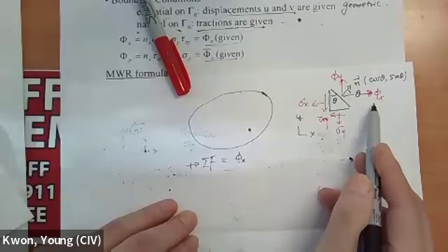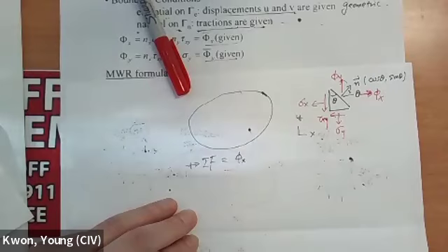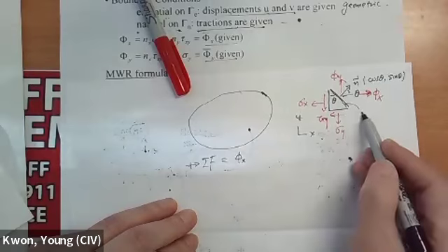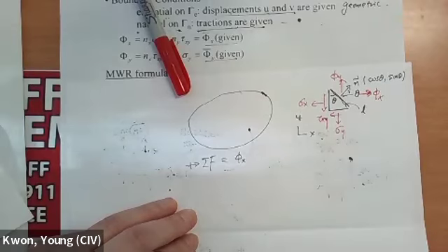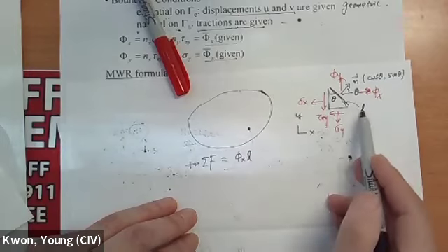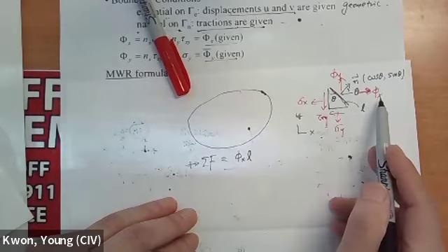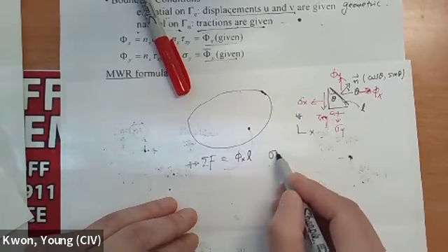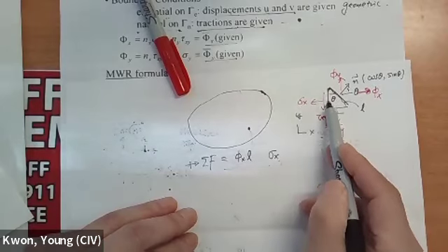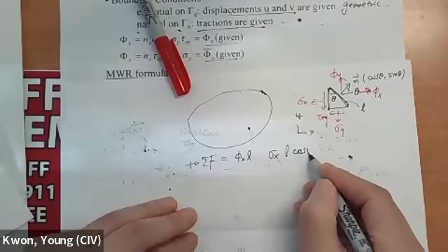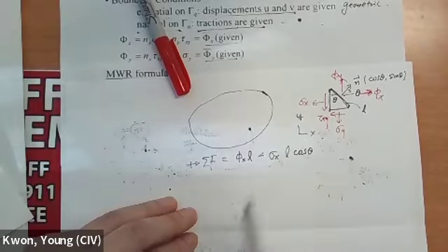Traction is like a stress. That's going to be the force per unit area. So multiply by this area. Let's say this area is going to be L. L is arbitrary, so just denote by L. Then Px times L, that's going to be the stress times L, so that's the force of that one. And which one has horizontal component? Sigma x. So sigma x times, what is this area? This area is going to be L times cosine theta and opposite direction, so minus sign, correct?